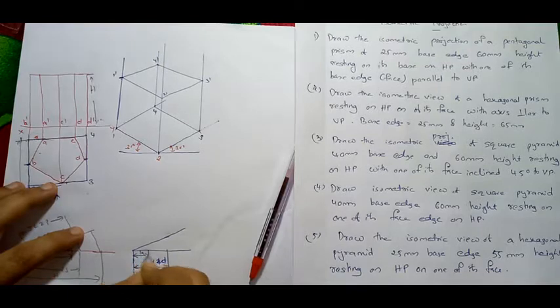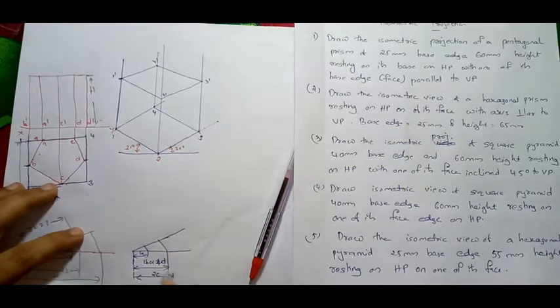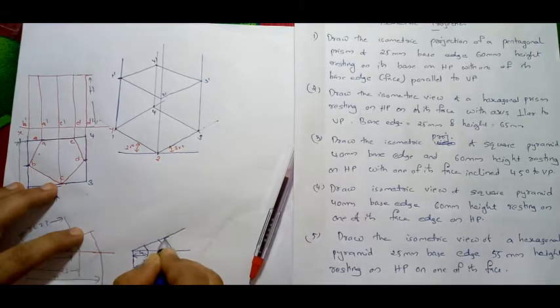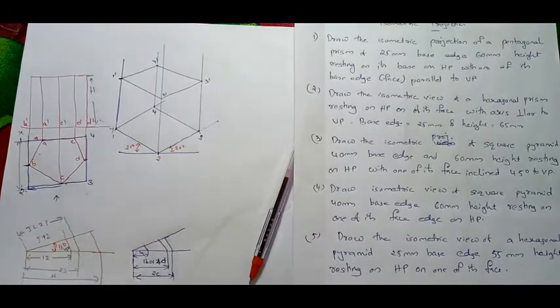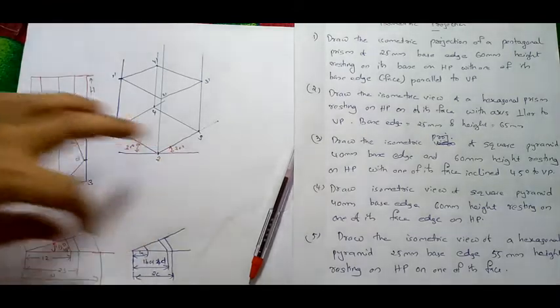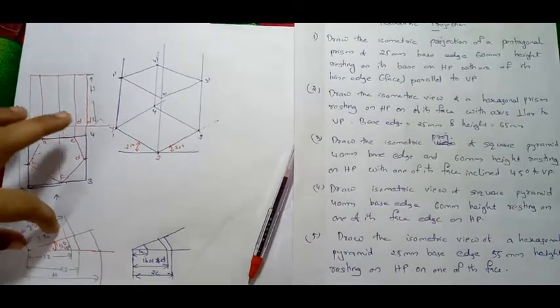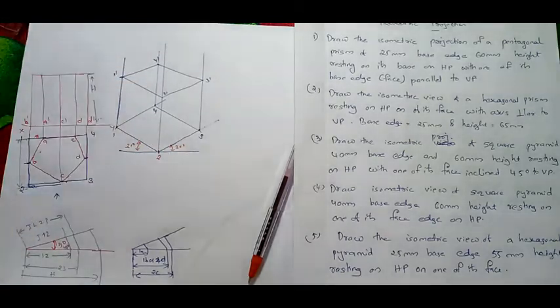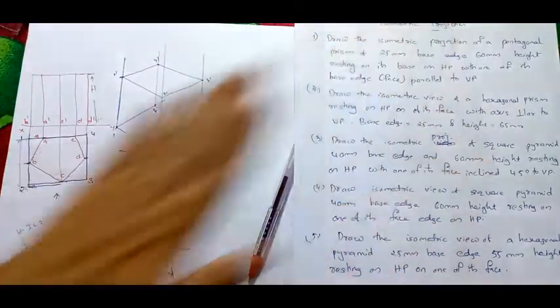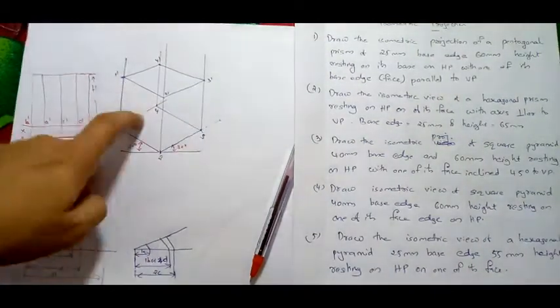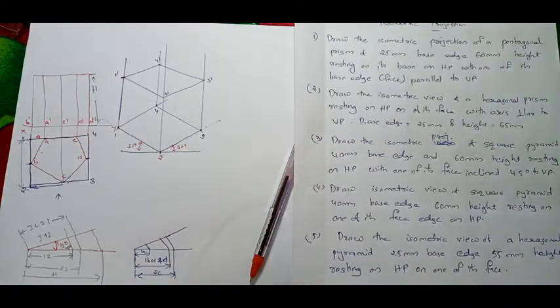1A. So for this, taking 45 degree, similar to the above, you have to find the corresponding isometric length. See, I have taken this length, cut it. So here itself you can cut and draw 45 degree, and take this isometric length. What I am going to tell is, never take true length while taking isometric projection. You have to take all the lengths while cutting using the scale only.